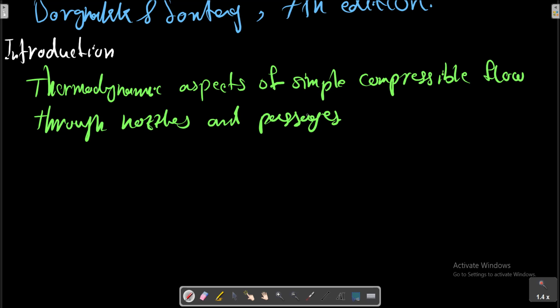The flow in a fan jet has several locations with high-speed compressible gas flow. It passes first through a diffuser, followed by a fan and compressor, then through the passage between turbine blades, and finally exits through a nozzle. A final example of a flow that must be treated as compressible is the flow through a turbocharger in a diesel engine. The flow continues further through the intake system and valve opening to end up in a cylinder.